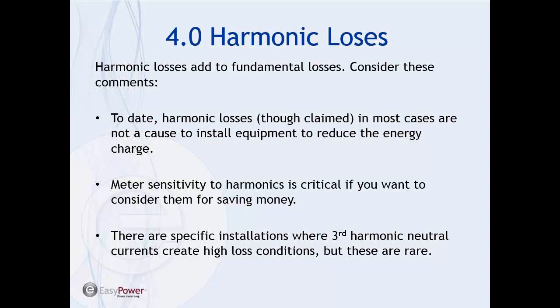But just know that. And also, if you're going to consider harmonic losses for energy savings, just understand how sensitive your meter is to those harmonics. Whether it can actually calculate the total kilowatts in fundamental plus harmonic, and how well it does it, is a pretty critical factor in whether you're going to save money or not. So you might want to do some evaluation on how sensitive the meter is, because you may save all these losses inside your facility, and then you get no benefit from it on the billing.